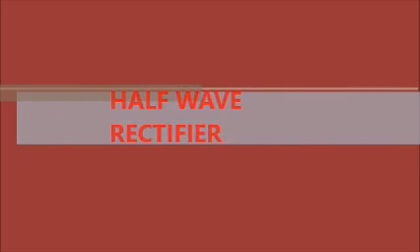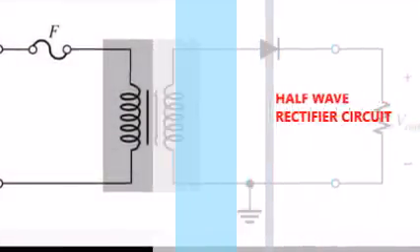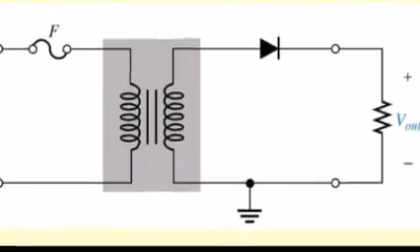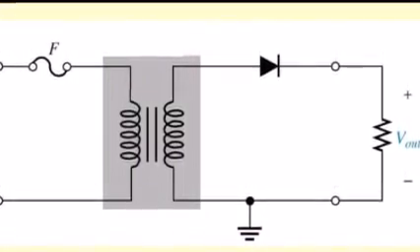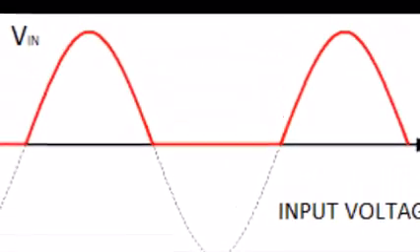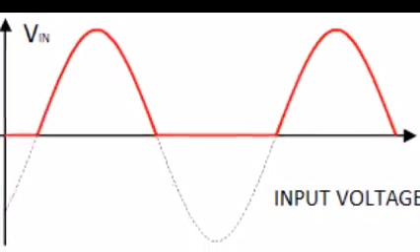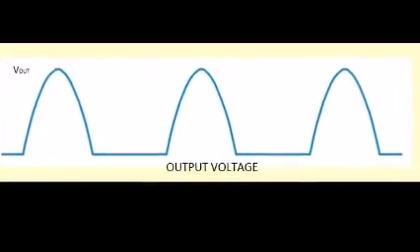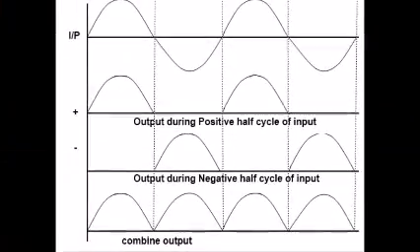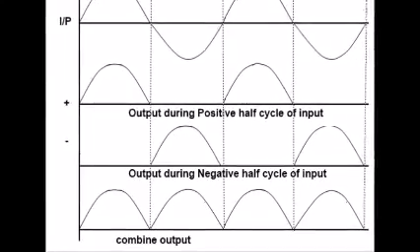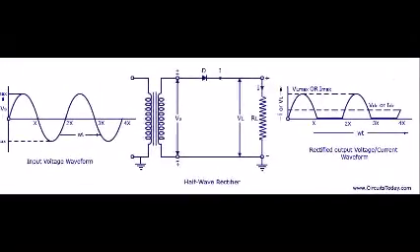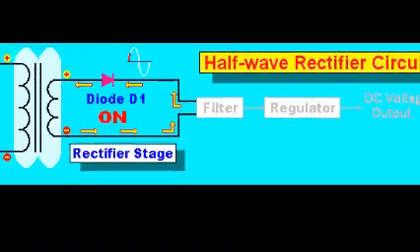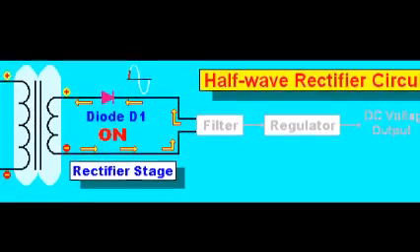Half-wave rectification. In half-wave rectification of a single phase supply, either the positive or negative half of the AC wave is passed, while the other half is blocked. Because only one half of the input waveform reaches the output, mean voltage is lower. Half-wave rectification requires a single diode in a single phase supply, or 3 in a 3-phase supply. Rectifiers yield unidirectional but pulsating direct current. Half-wave rectifiers produce far more ripple than full-wave rectifiers, and much more filtering is needed to eliminate harmonics of the AC frequency from the output.